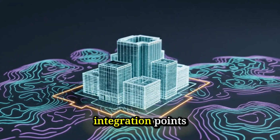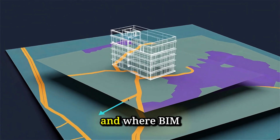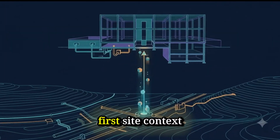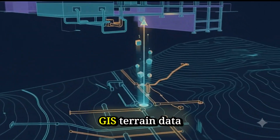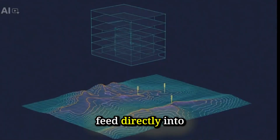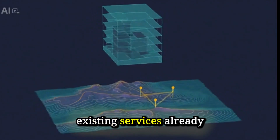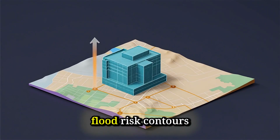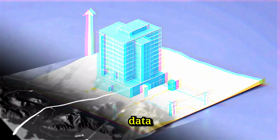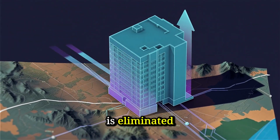There are 3 integration points where GIS intelligence feeds directly into BIM, and where BIM data returns to enrich the spatial record. First, site context into the model. GIS terrain data, utility mapping, and drainage routes feed directly into the BIM model's site setup. Accurate levels, existing services already located. Flood risk contours already embedded. The manual re-entry of survey data, which introduces errors and delays on every traditional project, is eliminated.